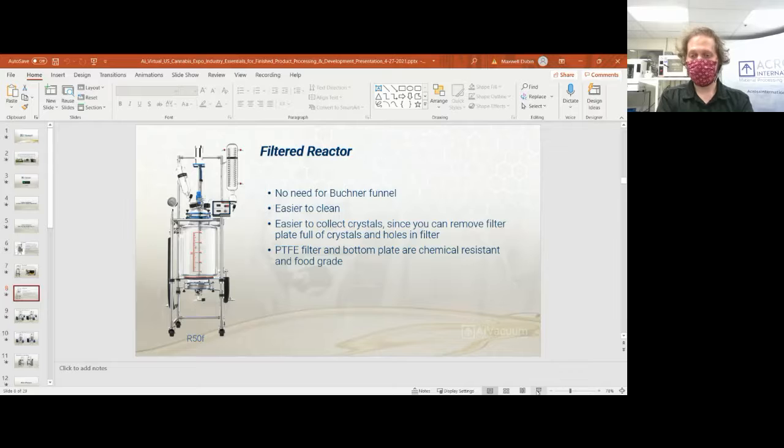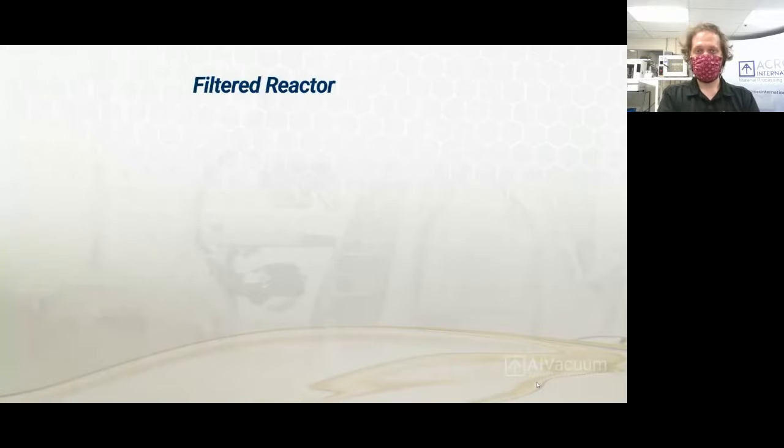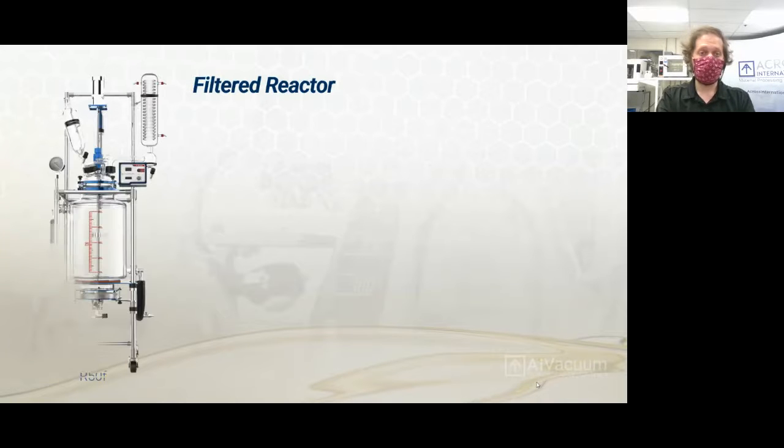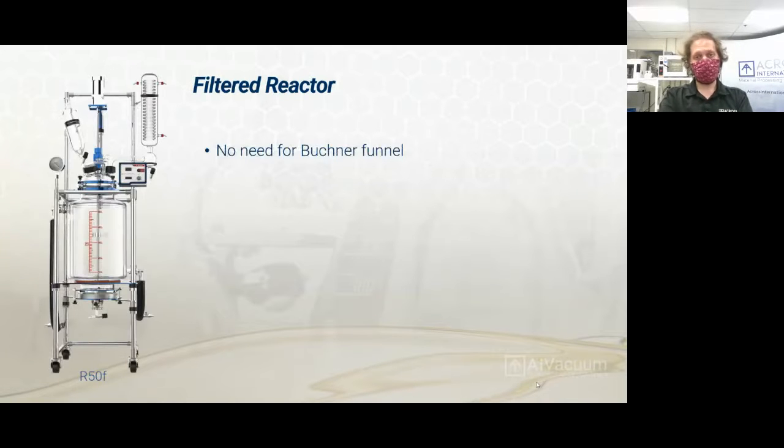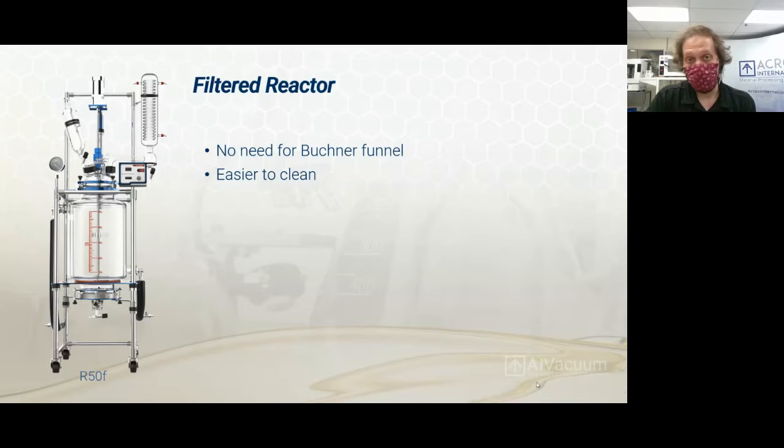They are PSI peer reviewed for C1D1 compliance with several solvents and can be pressurized up to 15 PSI while maintaining that peer review. In general, we've tested the stainless steel reactors up to 70 PSI if you do not require that third-party engineering peer review for compliance with your authority having jurisdiction, or AHJ, in your lab.